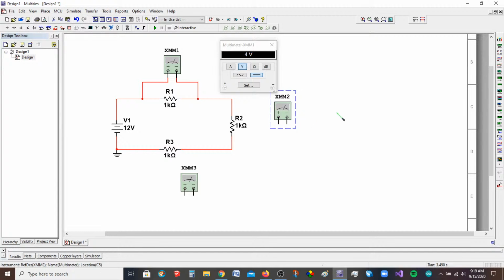Okay, so notice how I could just go ahead and give myself a couple of 90 degrees here to get up here to make this work, but this is just essentially another component, the way that Multisim sees it. So I select that and I can do Control R. All right, so that kind of makes the wiring a little bit nicer if you're worried about that. If you don't mind the squiggly lines, then it doesn't matter. It all works the same.